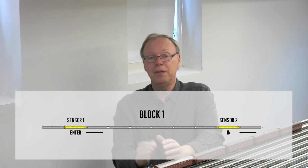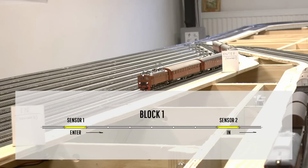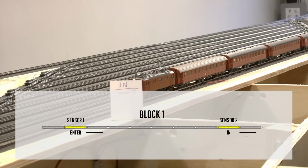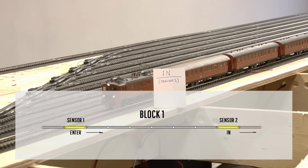As mentioned, it's better to design the block using two sensors. First, in the beginning of the block, you have a sensor which tells the system that a train entered that block. And then in the end of the block, you have another sensor, a second sensor, which tells you that the train now is fully into the block.